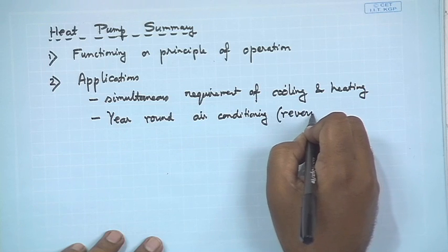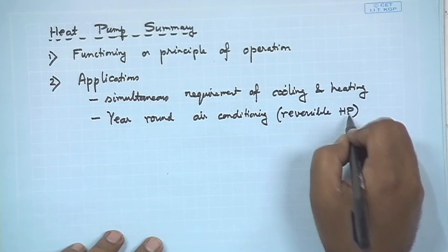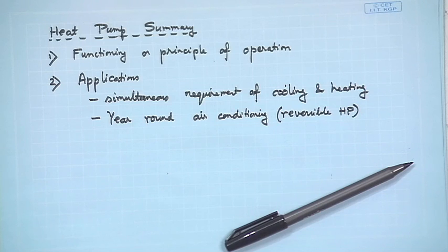Remember, we talked about a reversible heat pump where using a four-way switch we were able to switch the evaporator and condenser, or rather use the heat exchanger that we have inside the room as an evaporator in summer so that it leads to cooling, and as a condenser in winter so that it leads to heating. Okay. So we looked at this application, and it was a wonderful example of a heat pump. Again, remember that in summer while we had cooling by passing the hot outside air over the evaporator, we also had additional air at a still higher temperature at the condenser end.